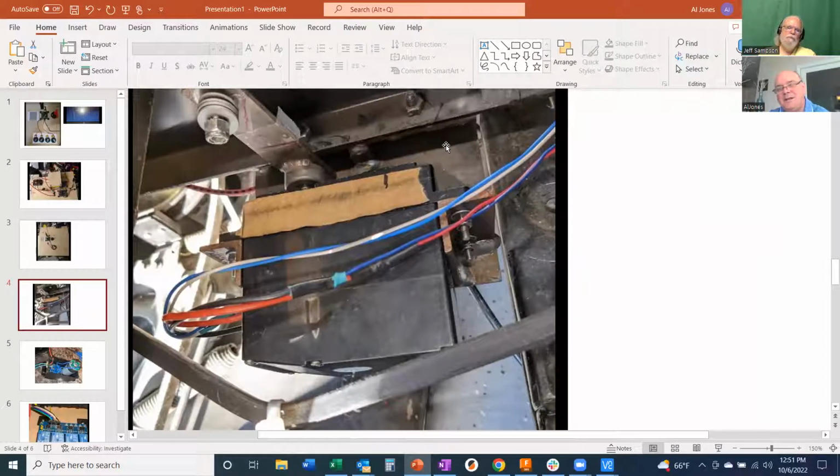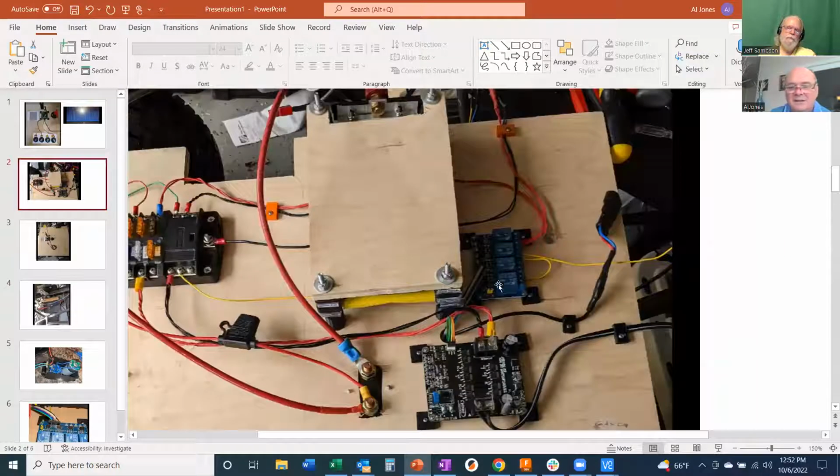And I want to be able to make sure that can't happen without, anyway, I'm going to control the power to the servo via the relay so that I can be reasonably assured that the microcontroller is up and running and sending a neutral signal to the transmission.